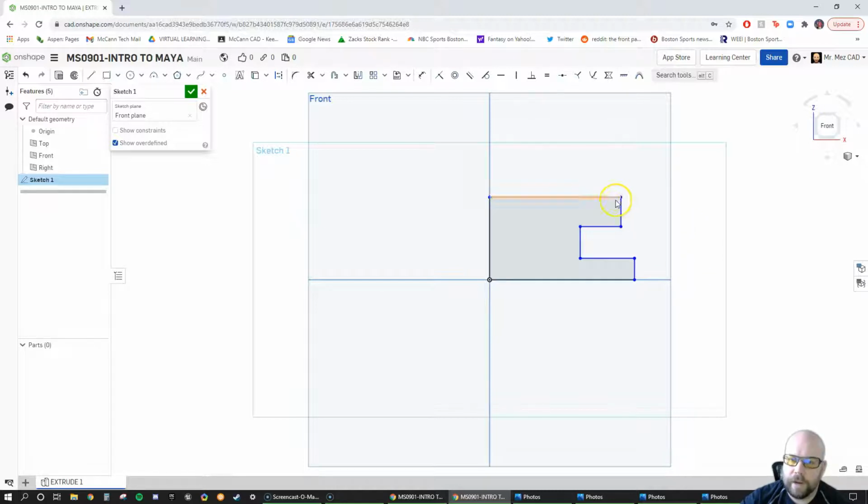But a very quick way to lose points on your project is if I go into your project and see blue lines, because that means you didn't go through and fully define the object, okay? So there's a couple different ways that we're going to fully define an object.